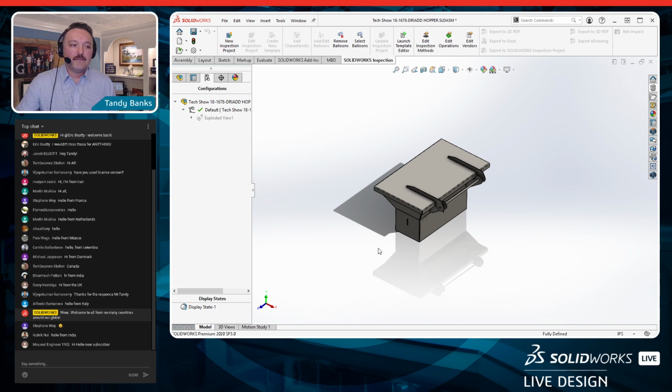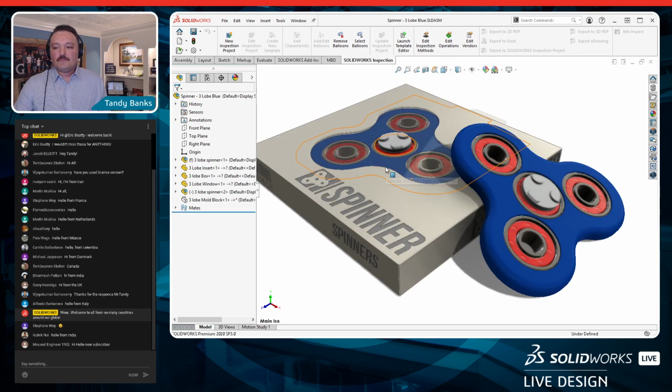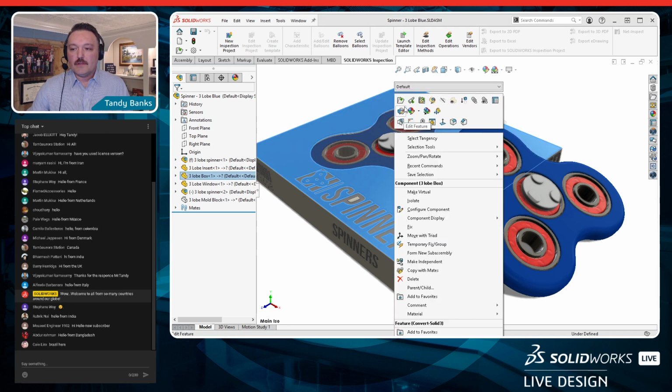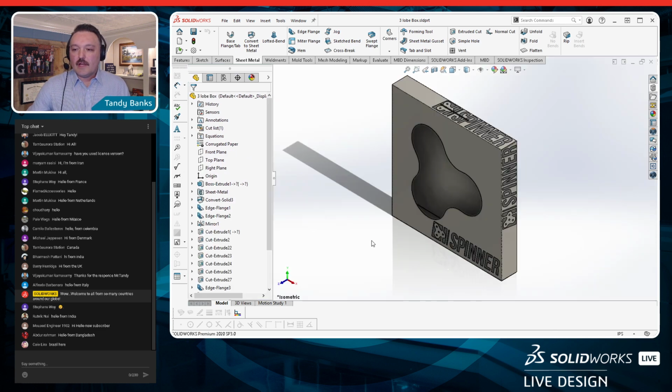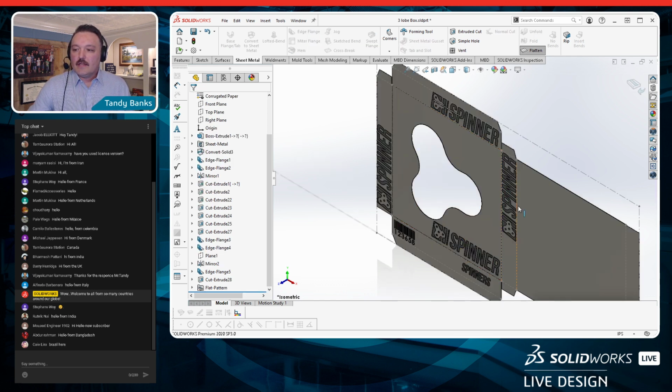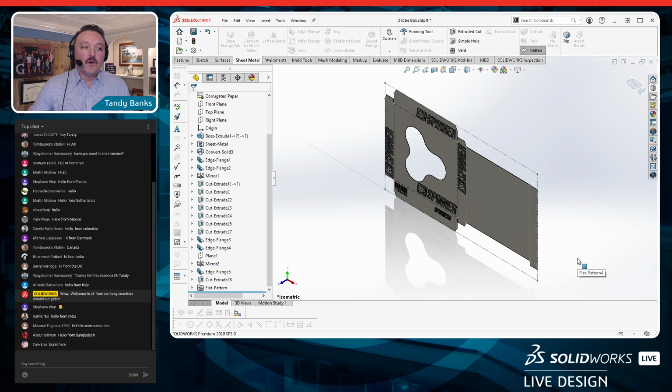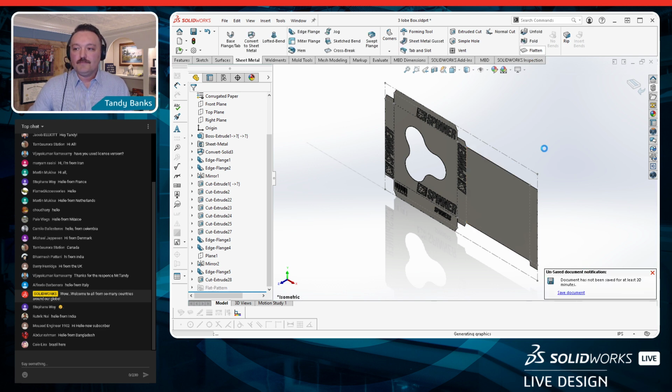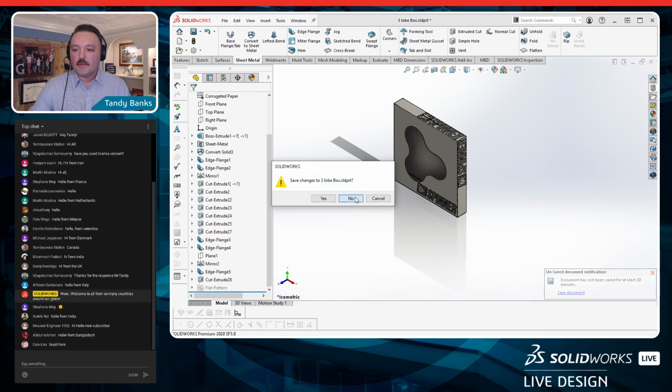But this would be the traditional sense of sheet metal. I'm going to show you a few different examples today of how you might use sheet metal functionality a little differently. Another of which is packaging. I've done some content out there on YouTube and other places on packaging design in the past, but you can see something like a box. We can use the sheet metal functionality to create cardboard boxes as well. We'll dig into some of the features used to create this, but again, that flat pattern is really what I'm looking for. Being able to click on an entity, hit the flatten button, and know the shape that we need to cut out is a really important aspect of those sheet metal tools.